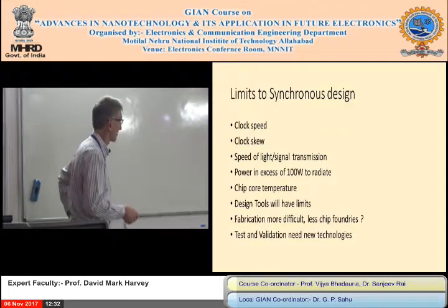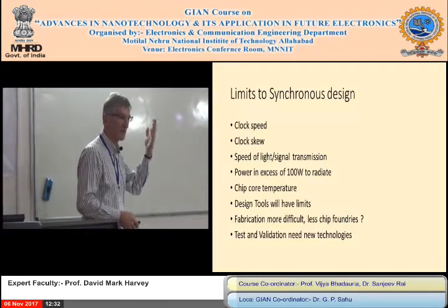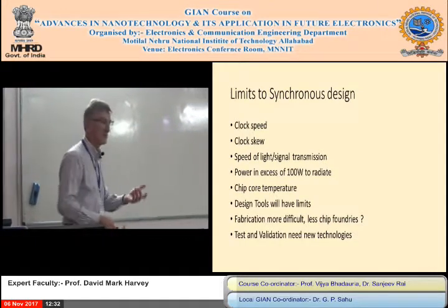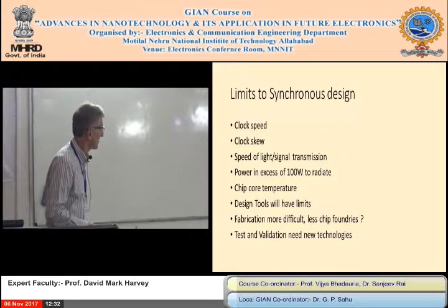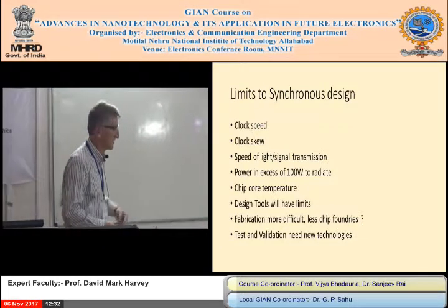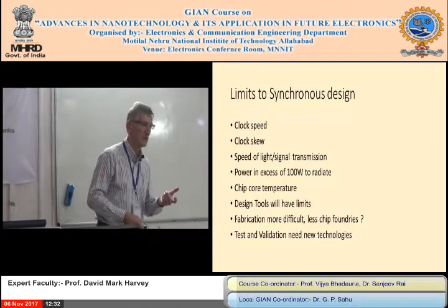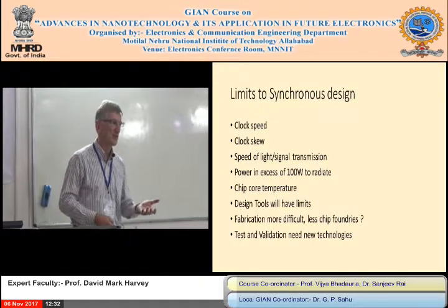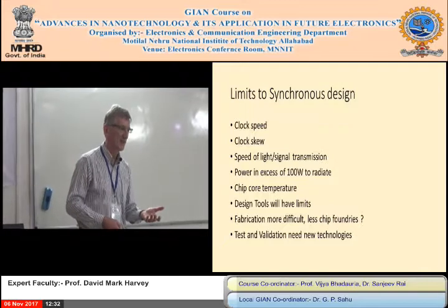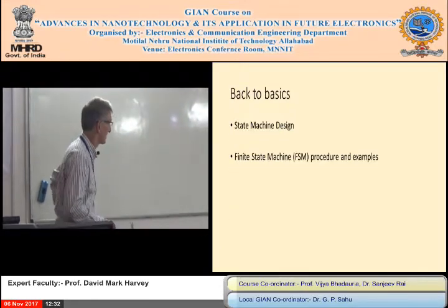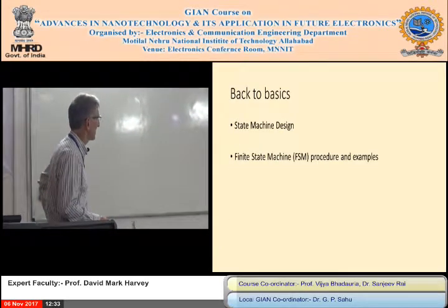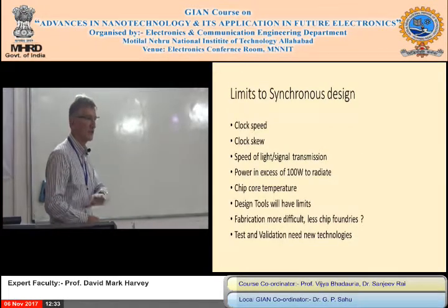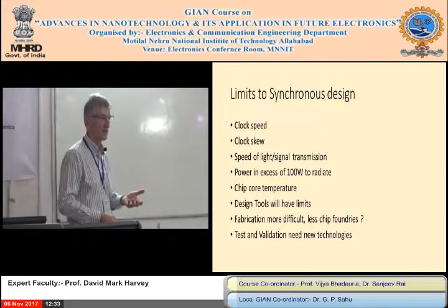So heat in excess of 100 watts is going to be difficult to get out. And if the fan has stopped, everything gets stopped. So the chip core temperature has to be kept down. Again, I've got a bit more on this later on, but basically if the chip core temperature goes up 10 degrees, the chip lifetime will go down by about half. You've got to keep it cool. Yeah, and it could be worse than that. And again, I said it at the start, what's the limits to the design? Well, the design tools will have limits. Design tools, even if you're a clever designer, can't do everything.